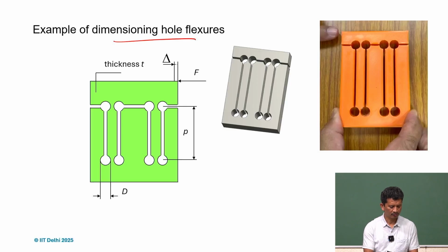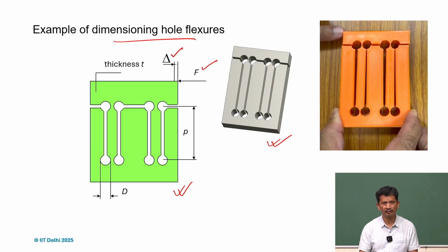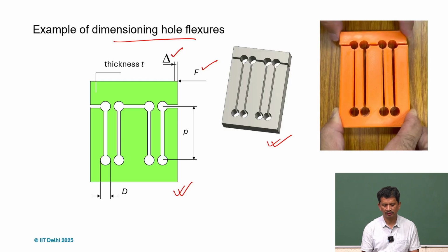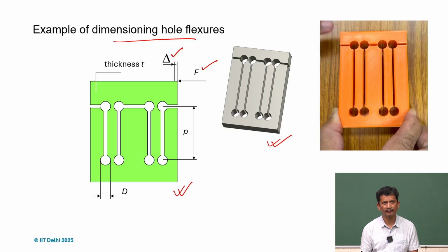We have a force acting and then we have a displacement. So this is a straight guidance problem, or a parallel guidance mechanism. That's what we achieved. I just developed a CAD model, and what we can see here is a 3D printed one, and when you apply a force, you can see a displacement.